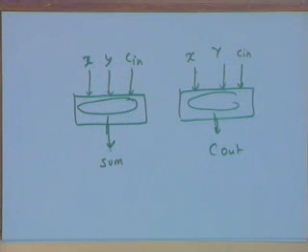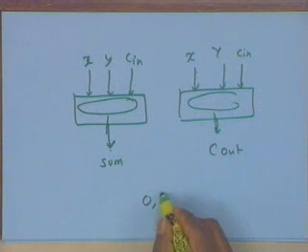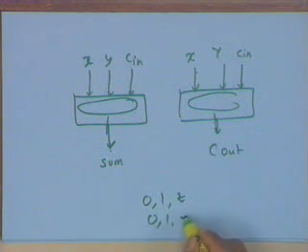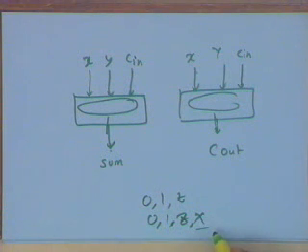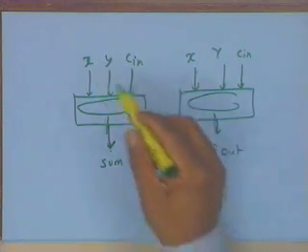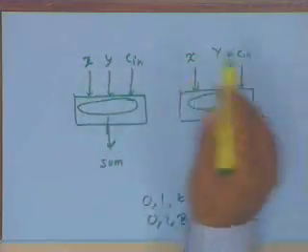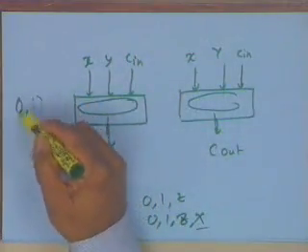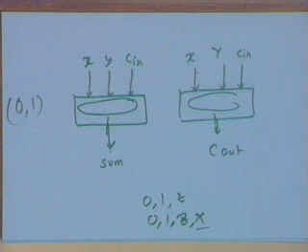The implication is, whenever there is any event occurring on X, Y, C in, what do we mean by an event? An event is anything which makes a change. X, Y or C in can become 0 to 1 or 1 to 0. There is a standard bit package available, which is a 2-level value. There are also some standard 3-level or 4-level packages available, where you can define your data to be 0, 1, Z, or 0, 1, Z, don't know. You can also define some multi-level. That is all up to you. Typically, for simple descriptions like this, we just associate a 0, 1 bit type. Once you go for tri-state logic, you have to include the Z also.